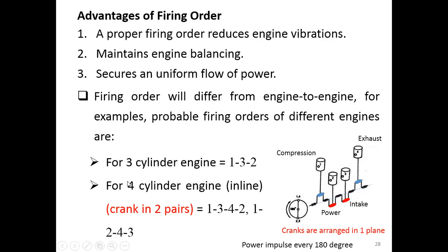For the 4-cylinder inline engine, the firing order may go like this: 1, 3, 4, 2, or 1, 2, 4, 3. And for this 4-cylinder engine, if it goes something like this, when you look at the cranks, the crank will be configured in 2 pairs, and these 2 pairs will be on the same plane.